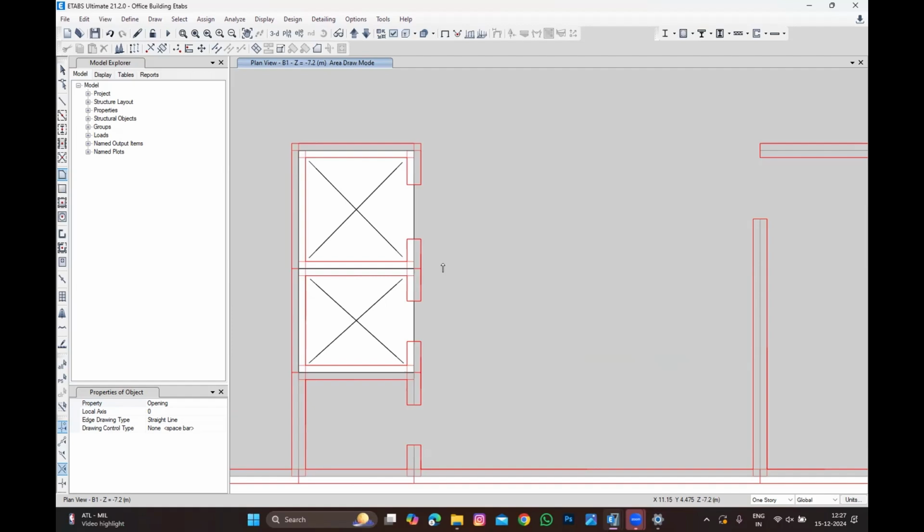First of all, it will lead to more shear reinforcement. Especially for a core wall, it will go for 12 mm dia shear reinforcement, horizontal reinforcement I'm talking about, 16, sometimes even 20 for certain floors. Then you may say it is wrong. It's required. I'm talking in terms of the structural model, to compensate the shear. Horizontal reinforcement mainly helps only for the shear. Just try to model the opening.